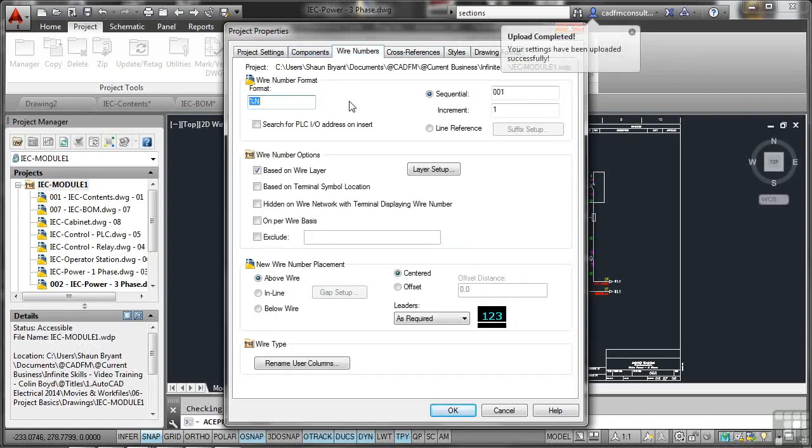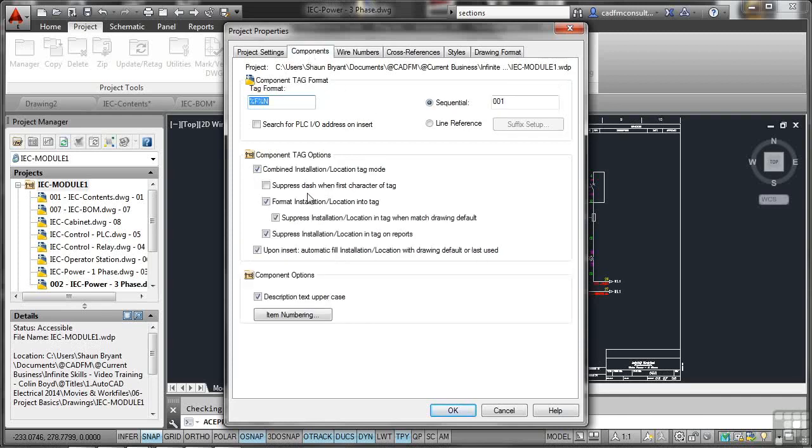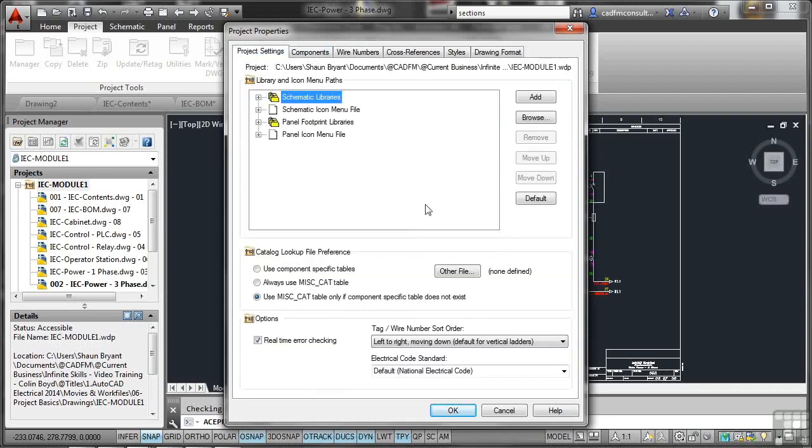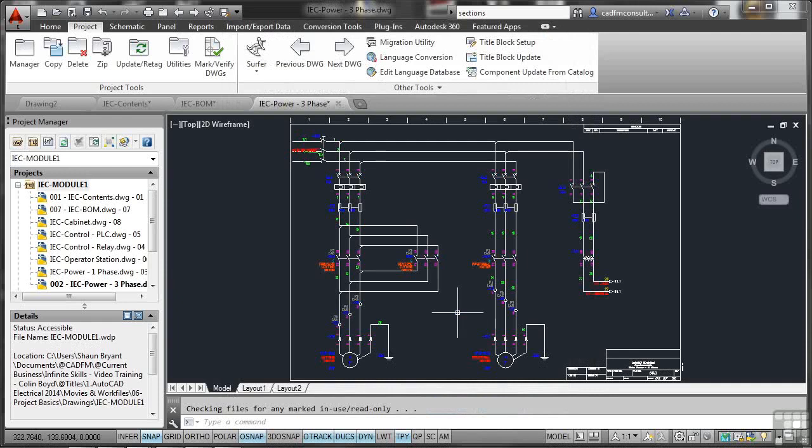You'll notice there as well on the screen, can you see that my Autodesk 360 is updating because I'm logged in? I've made those changes to the drawing, and it's updating that on my Autodesk 360 cloud account, which is great because obviously when I go and log in to 360 later on, I've got the most current drawing. It does that automatically for you. It's a very nice feature. Components wise, I can change the settings again as well, just like we did when we set up the project earlier. But I can go into this at any time. That's the nice thing about it. So I'll just cancel that now, and all of those settings are set up for that drawing.